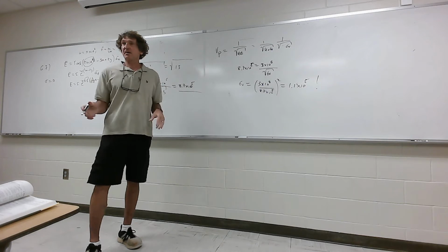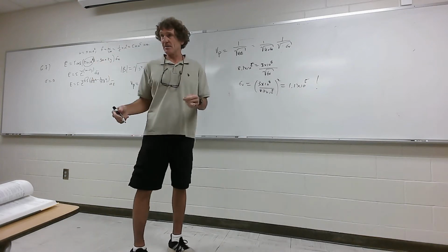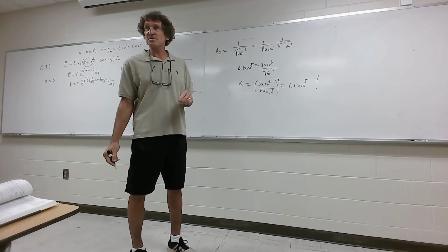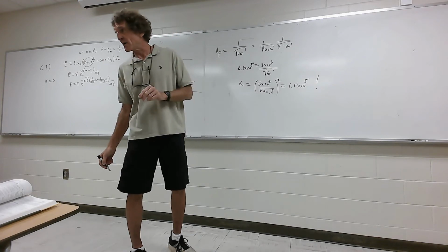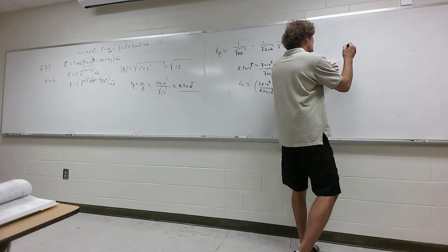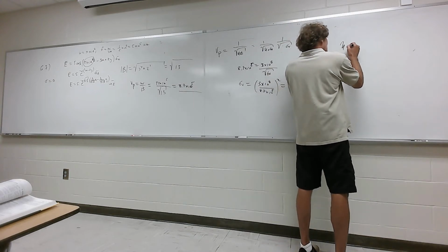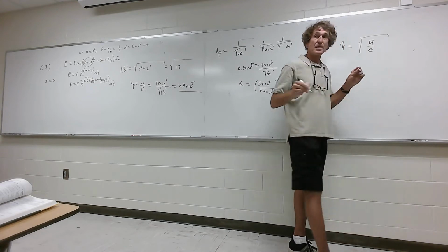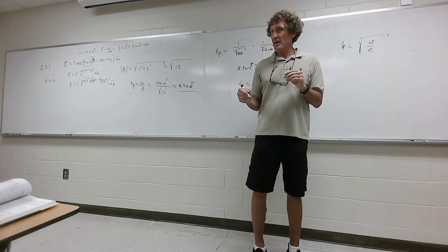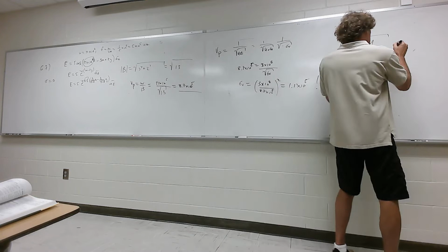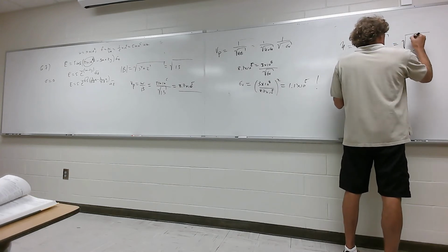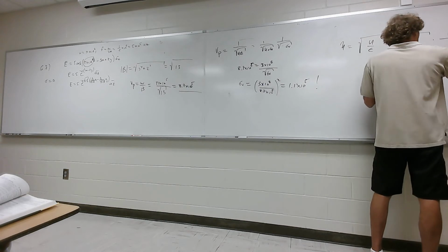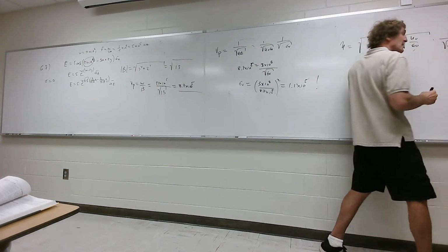All right. So now if we carried out the logic here, I'm going to show you how crazy it gets. If that's our epsilon relative, what's our value of eta naught? Well, our eta. Eta is what? Square root, it's lossless, so just mu over epsilon, right? Y'all follow me, class? All right, so we can say this is equal to the square root of mu naught over epsilon naught times what? If he said it's non-magnetic, 1 over the square root of epsilon relative, right?